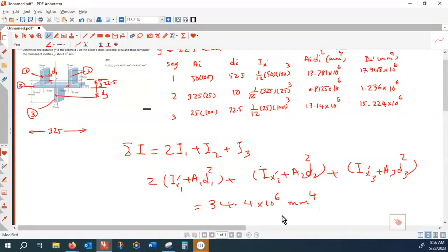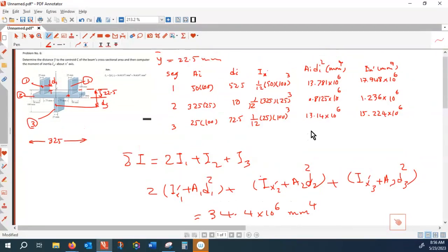When you are calculating moment of inertia, it could be in terms of meters, but meter is so big. So generally speaking, we write that in millimeters, and if the unit of the force is kept in Newton and everything else in millimeter, the stress would be megapascal. Okay, so that is the entire solution.